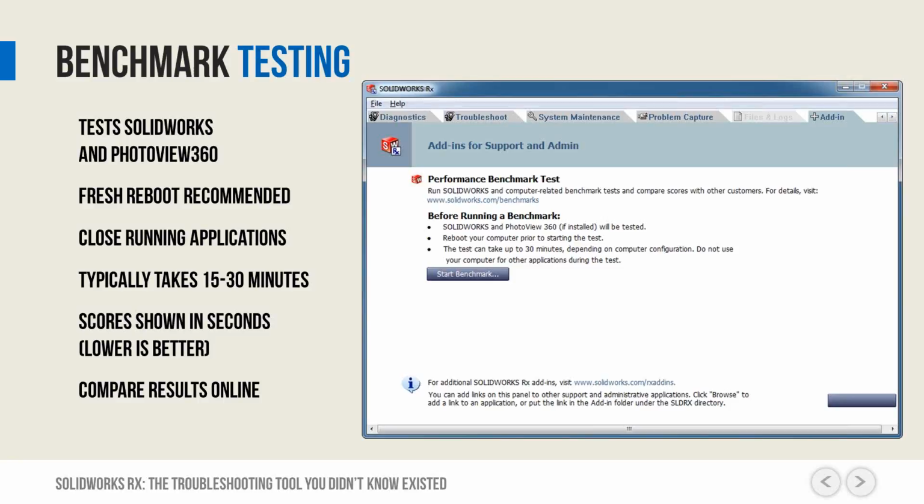If you can get that filtered down to, let's say, 10 users with identical hardware configurations as you, and yours is right in line with their numbers, then chances are SOLIDWORKS is fine, and there might be something else going on with your system that's slowing down the behavior as you use the software more and more throughout the day, some RAM limitations or something like that.